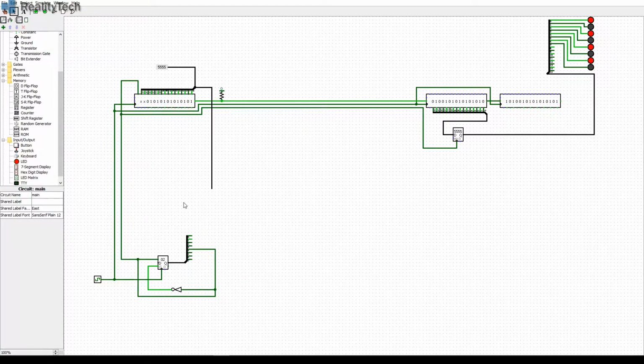But you can do this backwards, so you can generate the clock and reset pulses at this side and then send those out to the transmitting shift register, and that would allow you to read data back. There's all sorts of things you can use it for. It's a very handy little circuit.